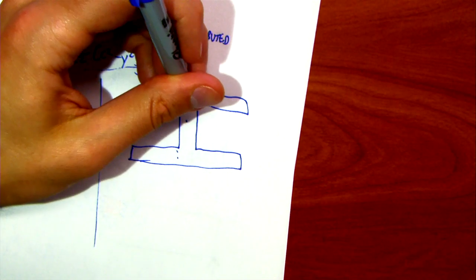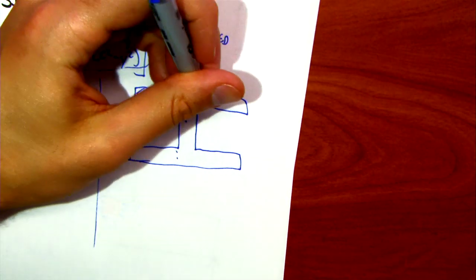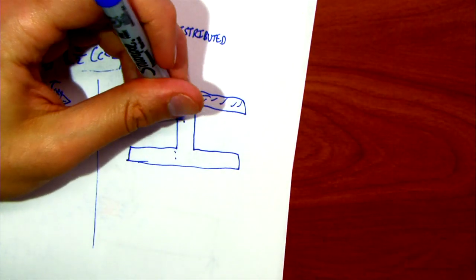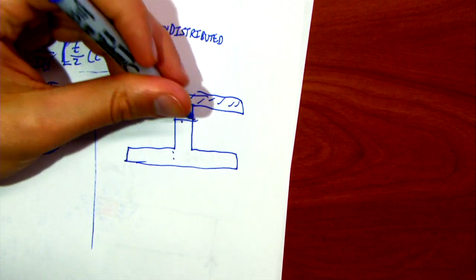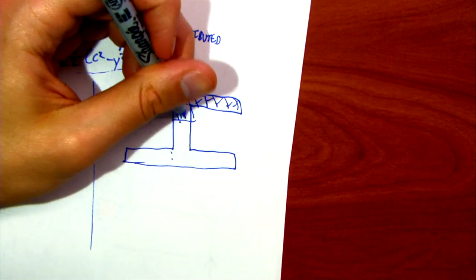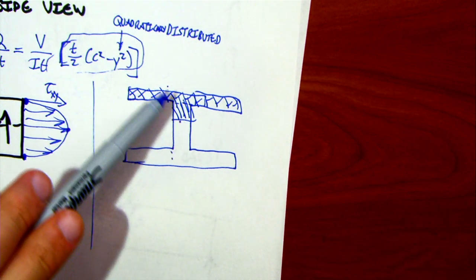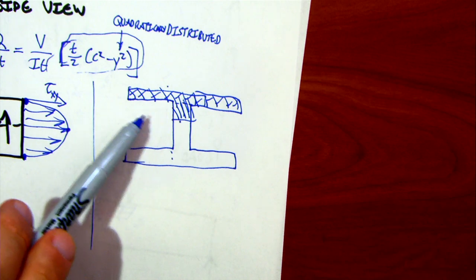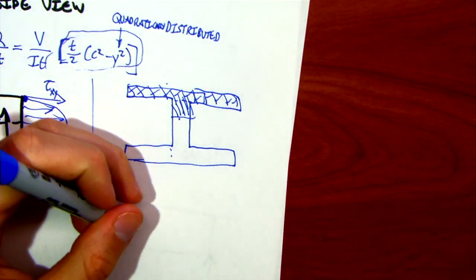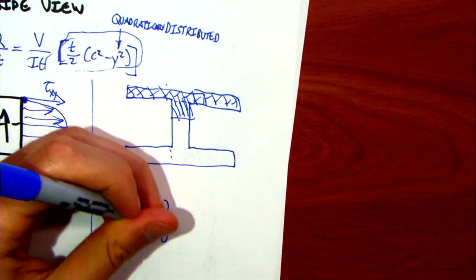If I drew a stress cube here versus a stress cube that included all that, those two things would end up having multiple thicknesses. The centroidal location would change and all of that, right? And as you might imagine, the thickness here is much smaller than this by like 3 or 4 times, right? So if I looked at the shear stress distribution for an I-beam,